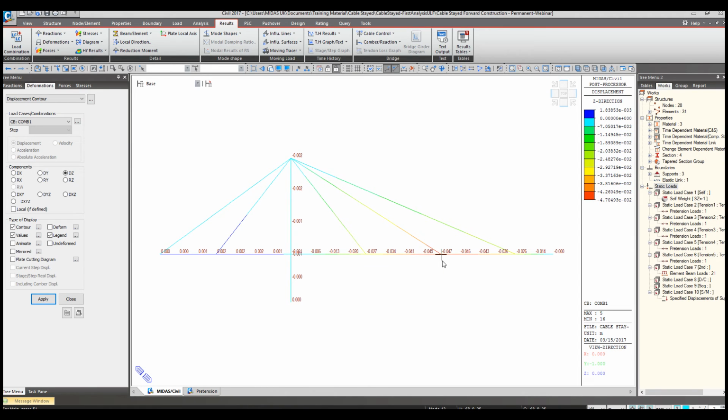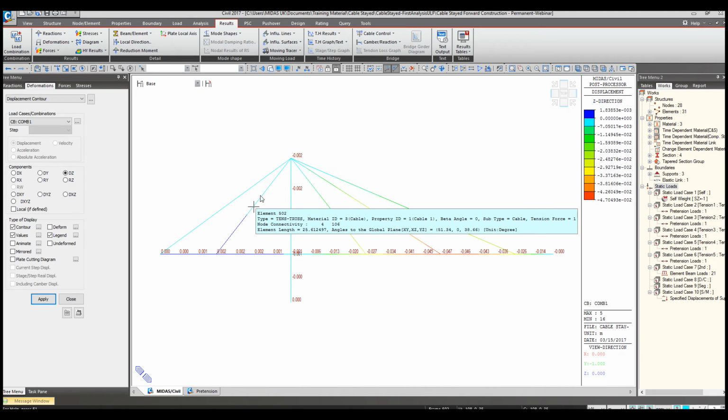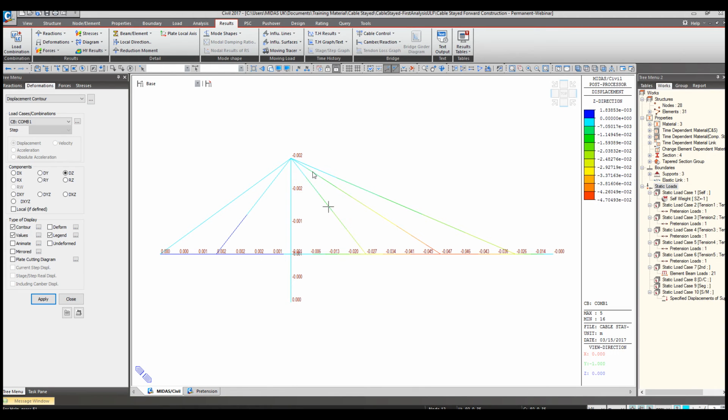I've rerun the ULF to make sure that all the constraints are respected, rerun the analysis, and as I can see, displacement for this combination, they are now within the limit. So if my main requirement for this bridge was to limit the vertical displacement, these pre-tension values, they're fairly optimized